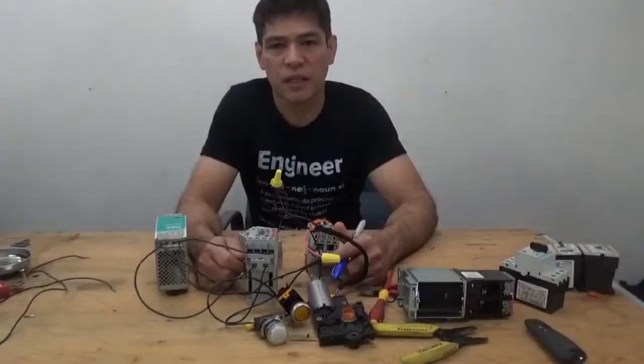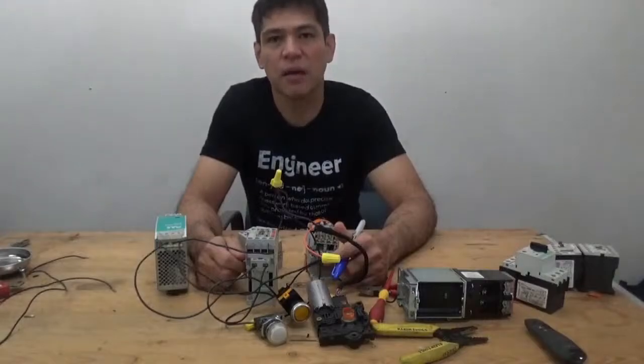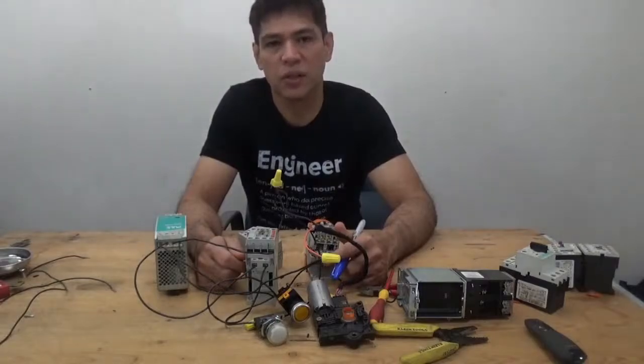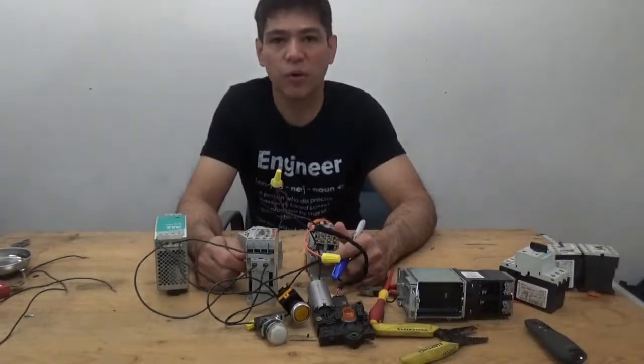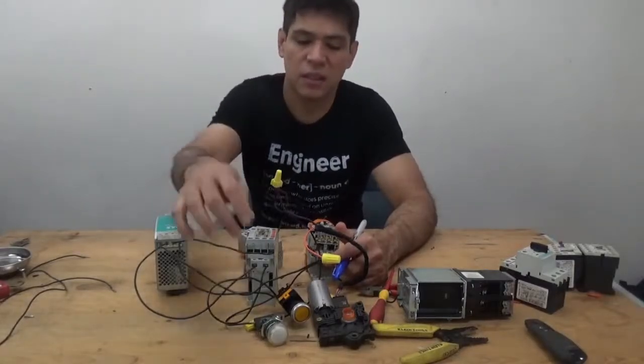Today, we're going to discuss motor starter. The purpose of a motor starter is to allow us to start and stop a motor safely, and it also allows us to start and stop from a remote operation. Basically, a motor starter is an electromagnetically operated device that starts and stops a motor load. It consists of an electrical contactor and overload relay, which provide short circuit and overload protection. Now we're going to our computer to discuss in more detail, then we do our practical exercises just like this.